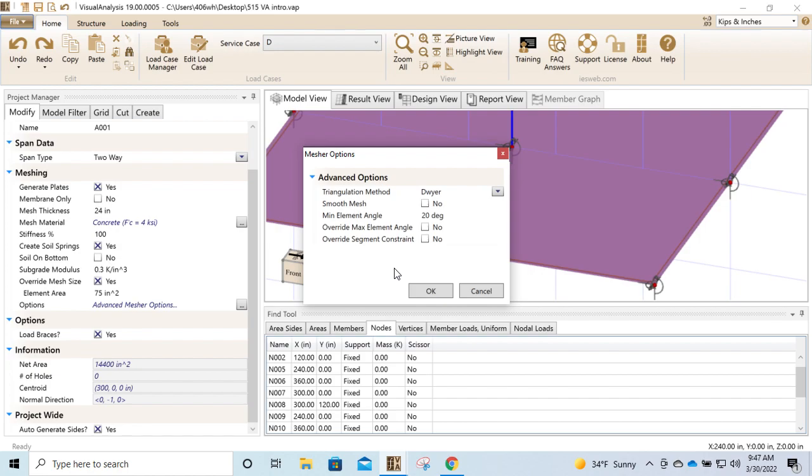Then the thick-thin is a totally different plate that's only looking at bending, out-of-plane bending. Yes, just looking at out-of-plane bending degrees of freedom, right? It's adding the translation, or the movement out of plane, of this footing. It also gives us the rotation for bending stresses, the rotation about the plane axes.